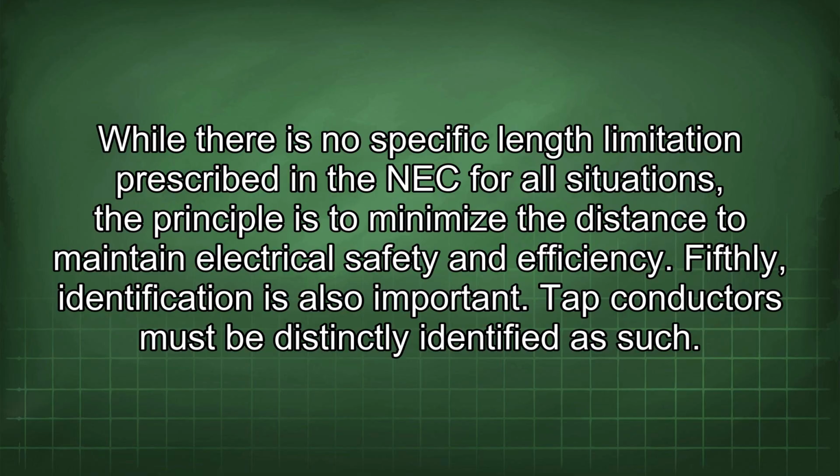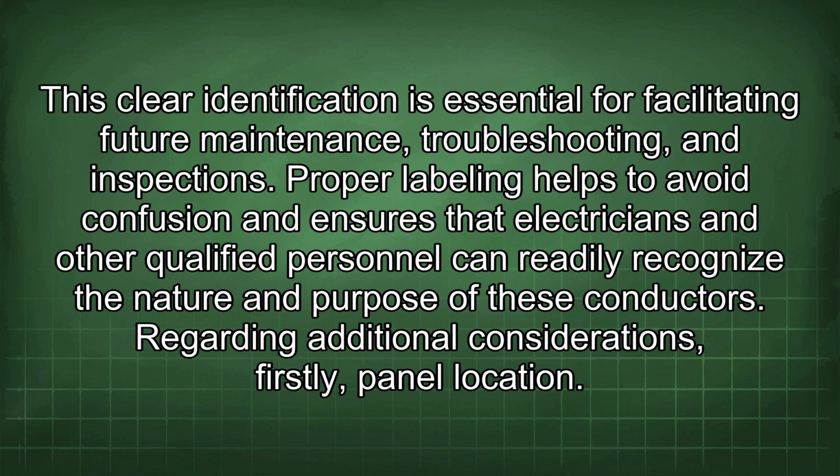Fifthly, identification is also important. Tap conductors must be distinctly identified as such. This clear identification is essential for facilitating future maintenance, troubleshooting, and inspections. Proper labeling helps to avoid confusion and ensures that electricians and other qualified personnel can readily recognize the nature and purpose of these conductors.